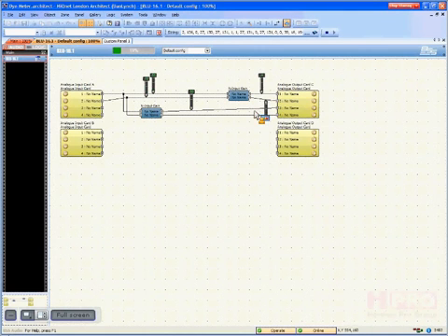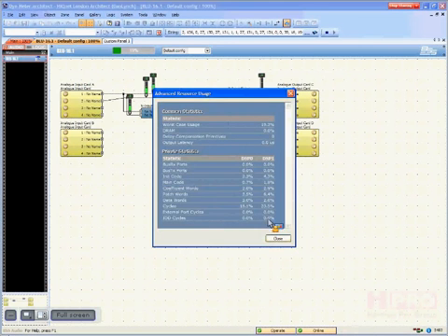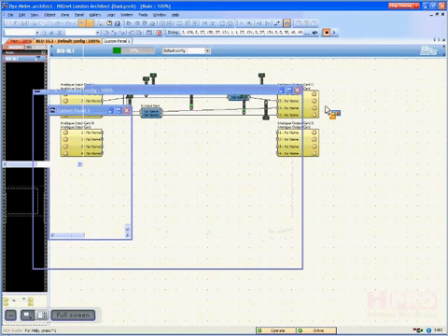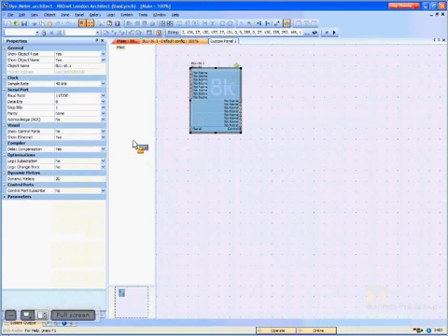Dynamic meters, now, they do take up DSP power, even when they're not being used, because the DSP has to reserve DSP power for all those meters. By default, your device will be capable of 2 dynamic meters. Look up here. Right now I'm sitting at 19.3% DSP usage. And a big part of that is because I've enabled 20 dynamic meters. What the heck do you need 20 dynamic meters for? Let's put it back to 2.